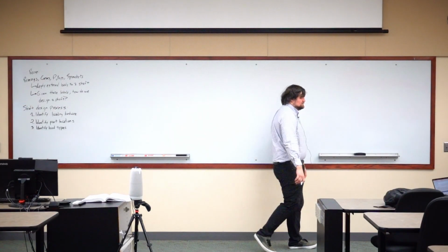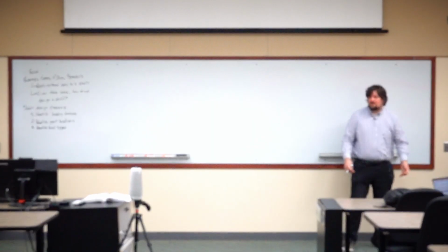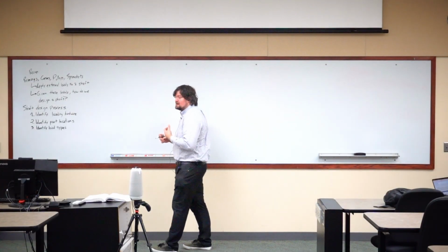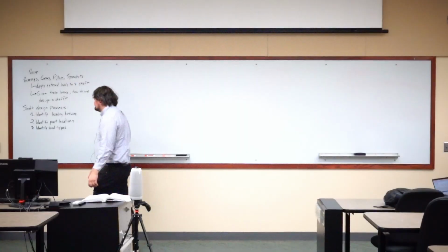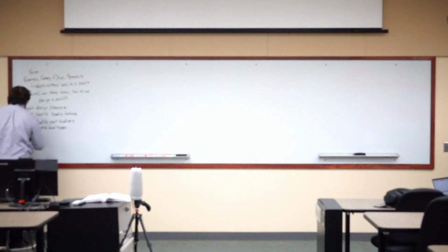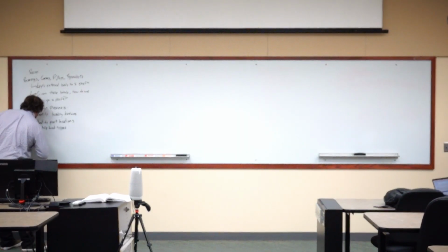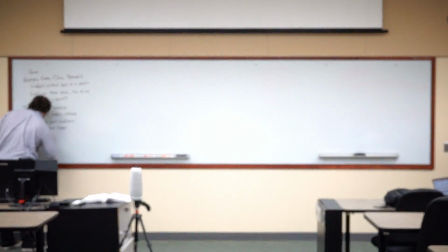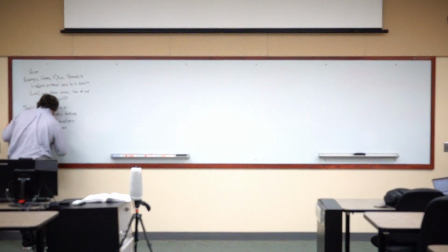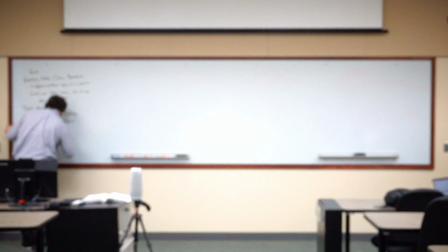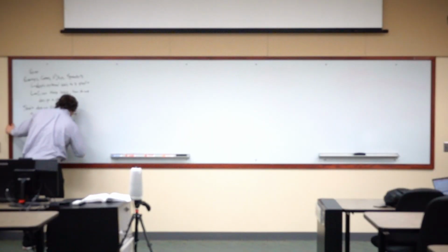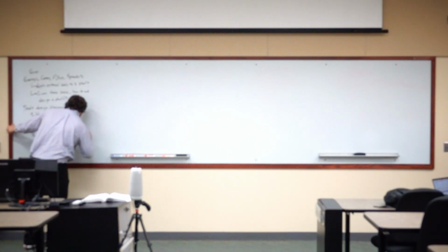Next one is, we need to identify load types. Is this going to be creating a load in the Y direction about a Z axis? Is it going to be creating a load in a Y direction about a Y axis? And then what we come up with is going to be our axial, bending moment, shear, and torsion diagrams.